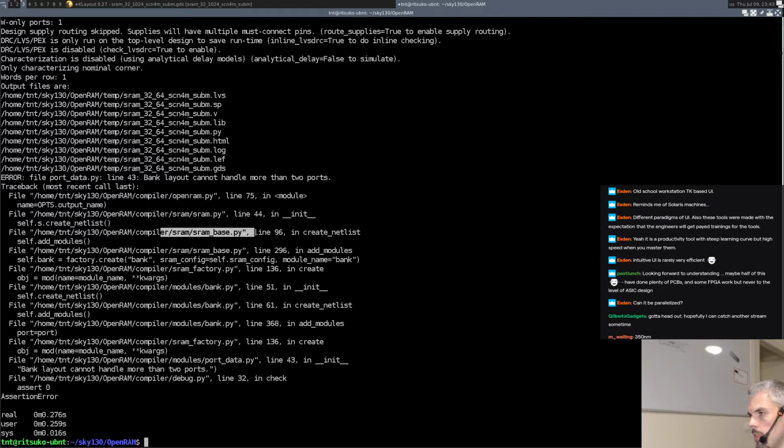But that's a lot of flip-flops to place, and you know that they have a very regular structure, right? So you know how to organize them and route them directly, and so using something like OpenRAM to generate that repetitive structure would probably be much better than just hoping that the auto router is gonna do it for you, basically.